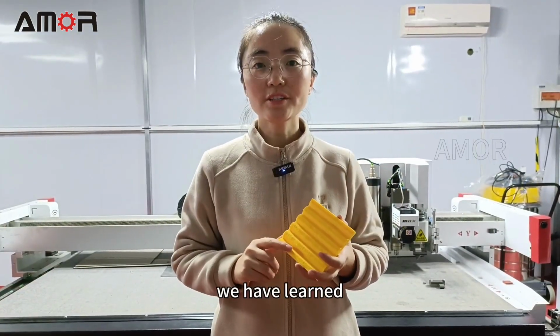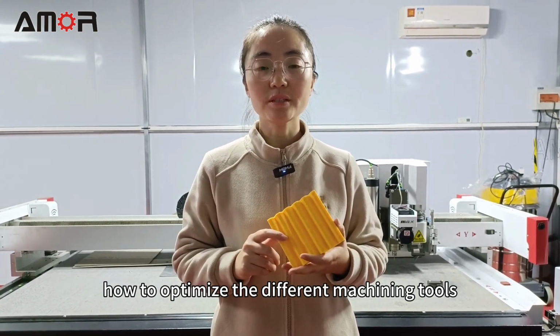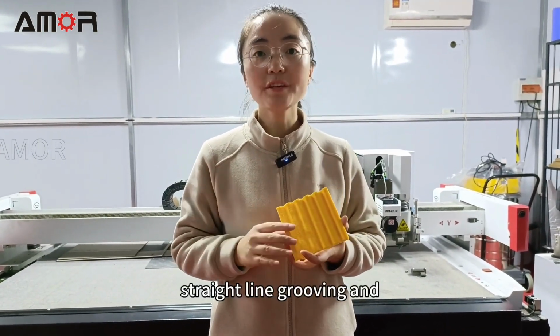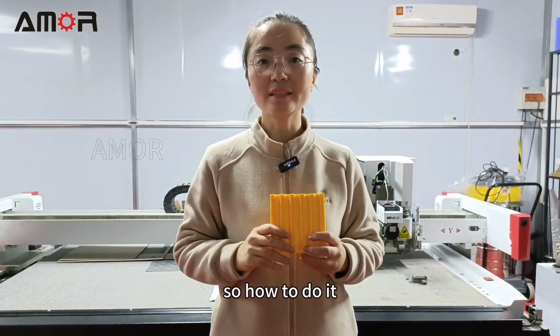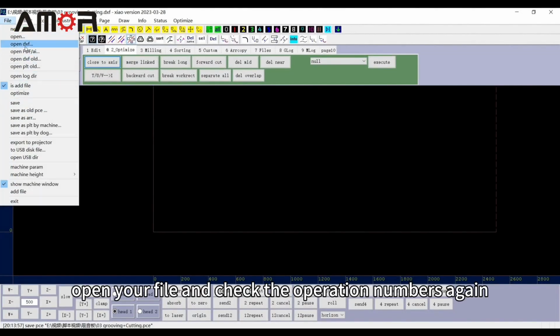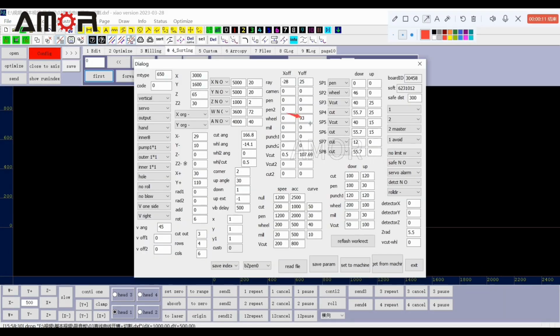Okay, we have learned how to optimize the different machining tools. If we need to cut straight line grooving and curved grooving at the same time, how do we do it? Let's show you. Open your file and check the operation numbers again. SP5 is for grooving and SP8 for cutting.